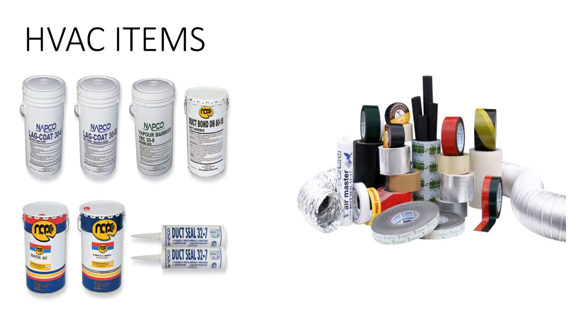If they mention any details about the vapor protection barrier, then you have to provide this canvas cloth. This canvas cloth will be wrapped around the duct insulation. Typically when you are going to wrap the canvas cloth around the duct insulation, you will dip the canvas cloth inside this vapor barrier protection. Then you will make that a vapor barrier protected canvas cloth, then you will wrap it around. Even before you wrap the canvas cloth, you have to dip it inside this vapor barrier compound.